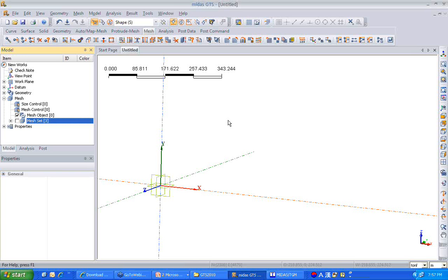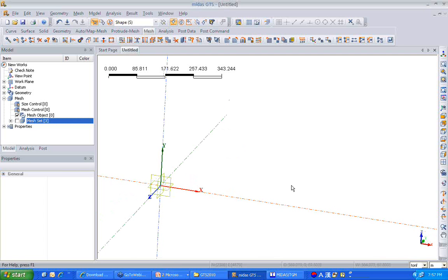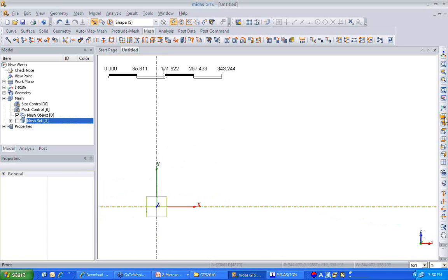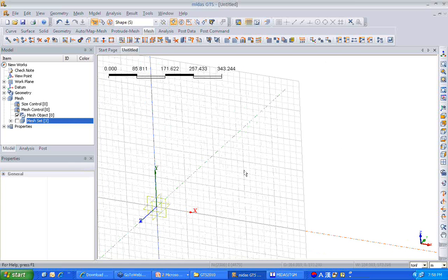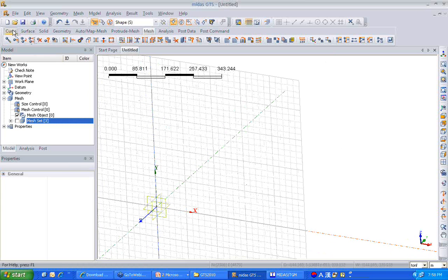Right now we have seen 8 nodal hexahedrons or 4 nodal tetrahedrons, but auto meshing a 2D face and then extruding it to 3D, we are going to create 6 nodal pentahedrons. Let's see. So for this, let's create a rectangle.